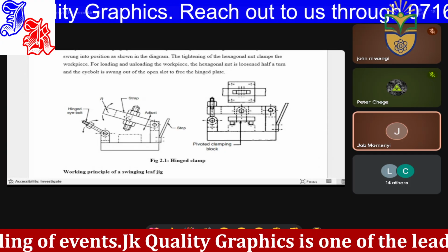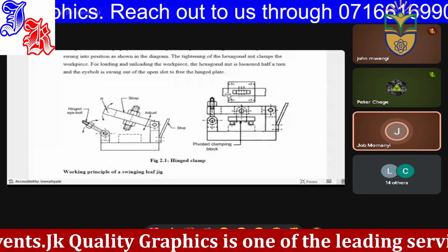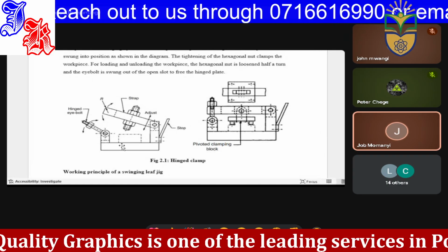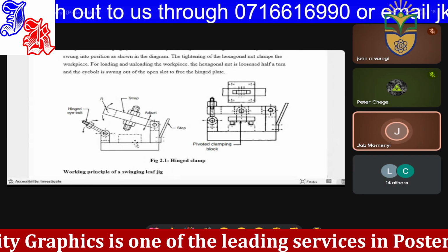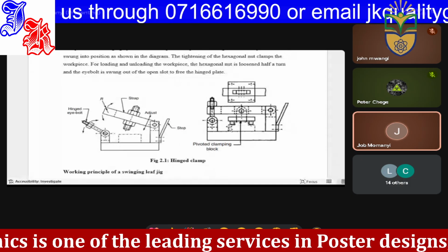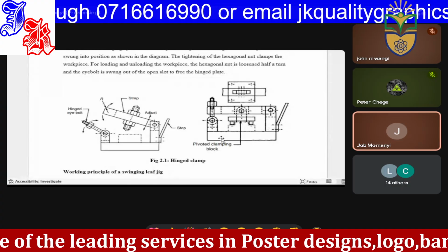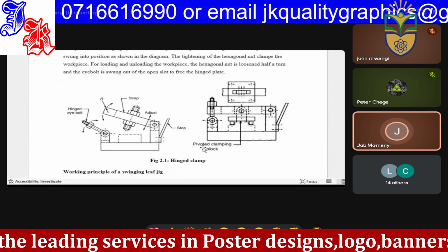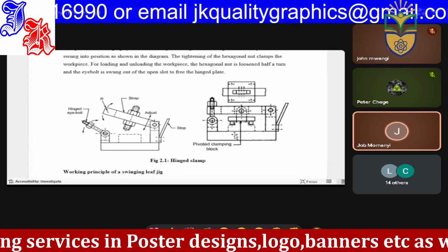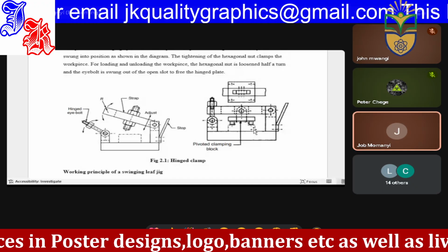You can think what you can do with this design so that you can come up with your own design. For instance, you can see we don't have the lower locating pins. You can introduce and remove this supporting bifolded clamping block, and replace it with the locating pins.